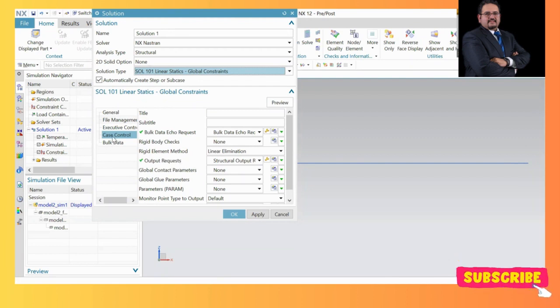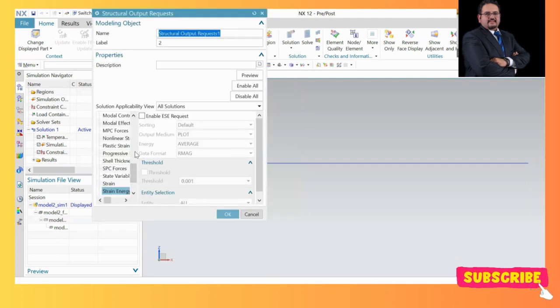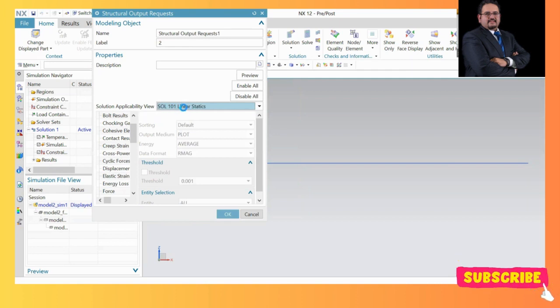So this is in case control. If you click case control, you come here to the output request, and this is edit. If you click on this signature icon, if you click on edit, it will open and show the different outputs that can be there. So for example, this is showing all different types of outputs. I can be very specific. I can say I want to see the outputs related to this solution. So now it is showing me only the outputs related to this one.